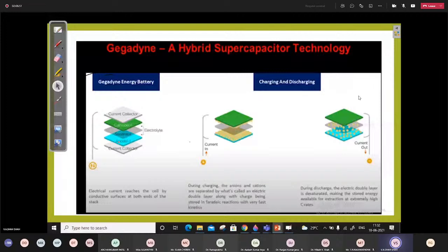And whenever this load may be again a bidirectional load, that means it can sink and source the current, at that time this switch will come into the picture and it will operate and put the additional charge into the supercapacitor. This battery switch will be only in on and off mode, while this one is in chopping mode. We have to chop it as per our requirement, and either we can have power transfer from supercapacitor to load or load to supercapacitor. And the battery will provide power only in one direction whenever the load is demanding power, maybe along with the supercapacitor or individually.